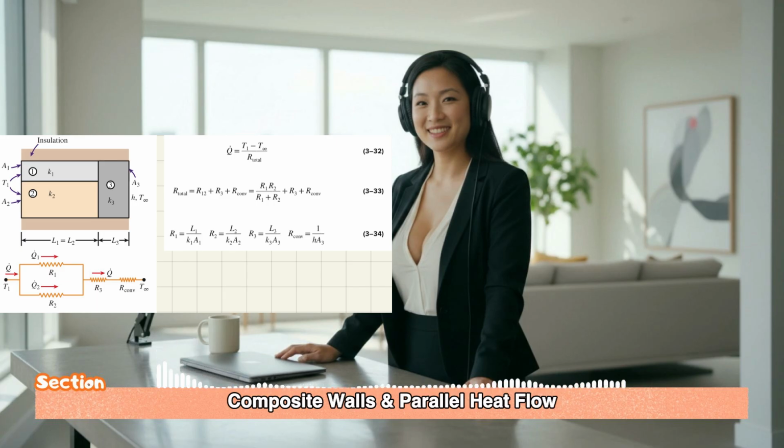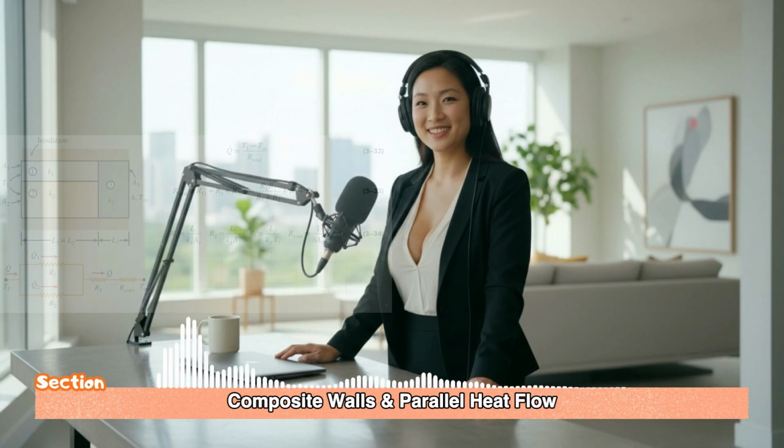You got it. It's a step-by-step reduction of the network. And it yields a surprisingly accurate estimate of the overall thermal performance of the wall. But we have to acknowledge the limitations. The heat flow isn't perfectly straight. It curves a little bit near the studs. So this 1D series parallel model is an approximation.